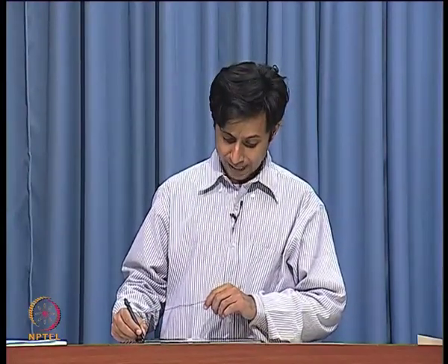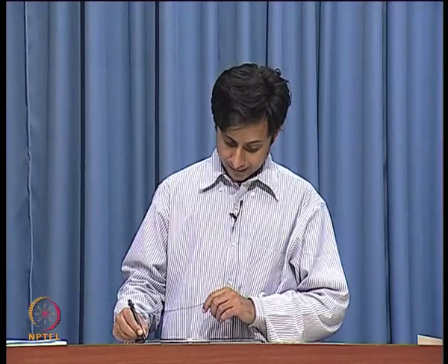All right. So, in the last class we ended on the note that I can potentially move the LO to the layer of transistors on top, and I can move the RF to the layer of transistors on the bottom. If I have RF on top, LO at the bottom, no problem whatsoever. I have some matching issues. How do I match the RF signal that is coming from the LNA to the input of the mixer?